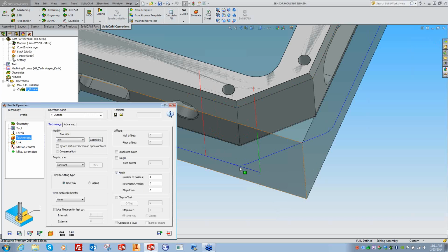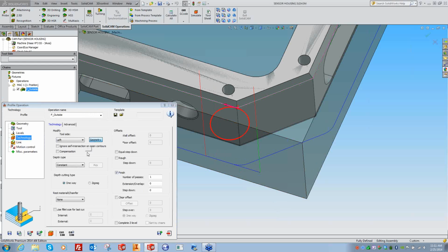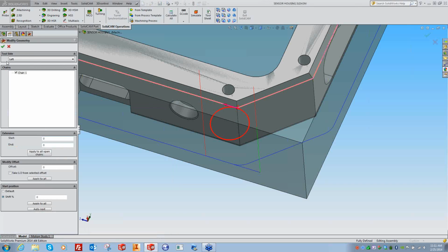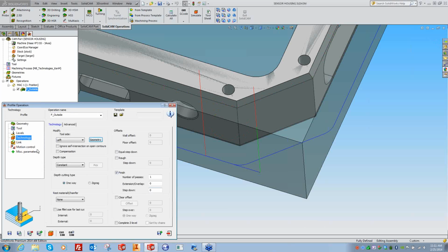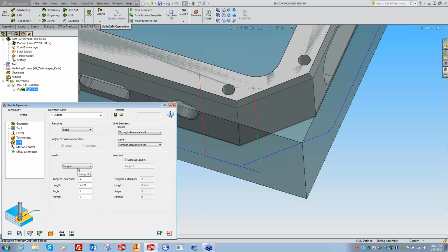Now you notice that we came around that corner, so we would need to put in that if you're going to do a straight lead in, lead out. I'm not going to worry about that. I'm actually going to turn on an arc. So let's do a 250 radius, 90 degrees arc.